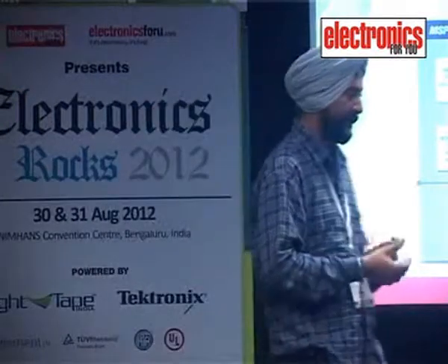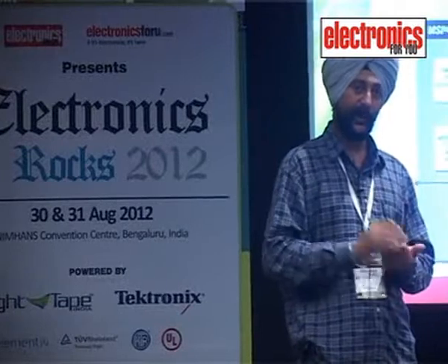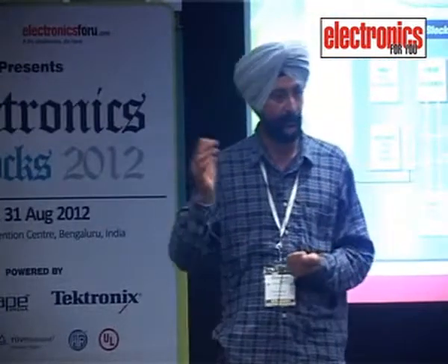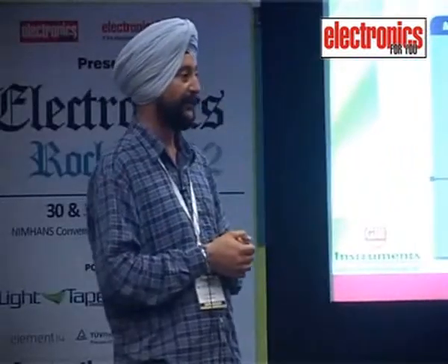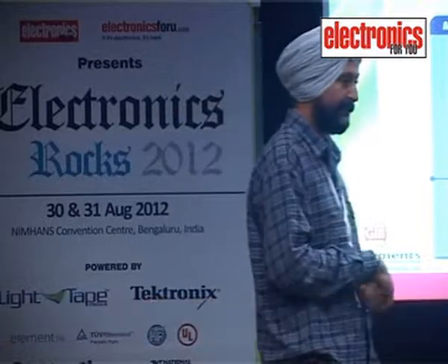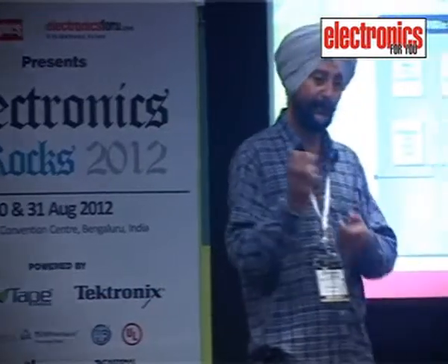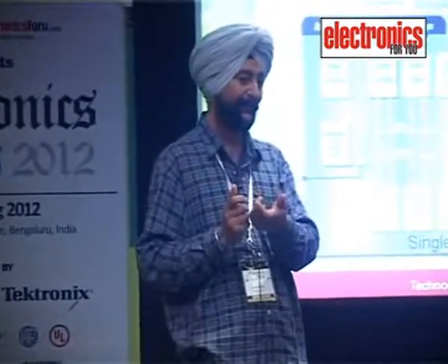In the same way, DMA can be used with a UART also. You are uploading some information from this system or you are downloading some information. DMA can be used along with the MAC also, where on the background you have to run, let's say, FIR filter. So DMA will help you to get these samples from ADC, right?